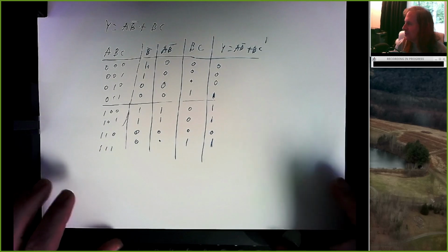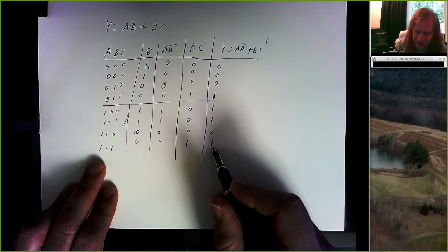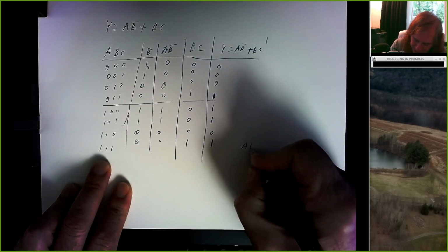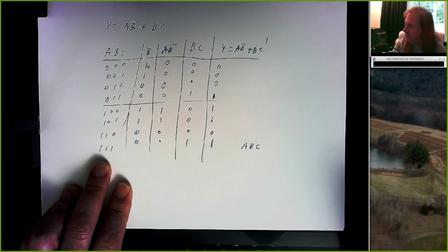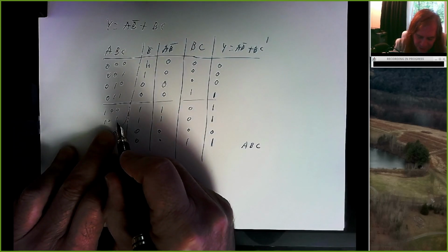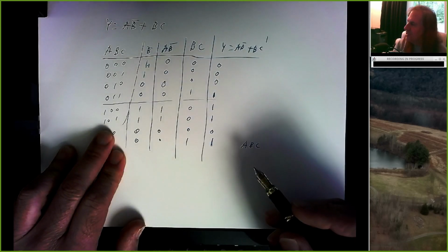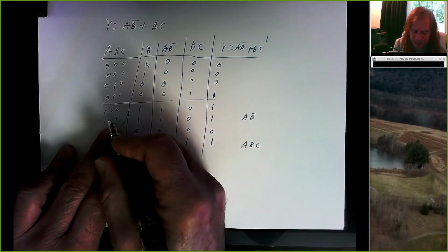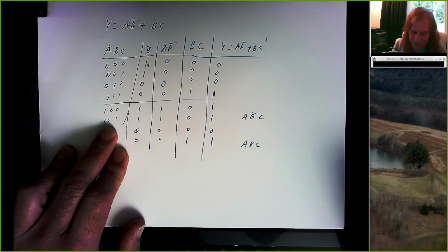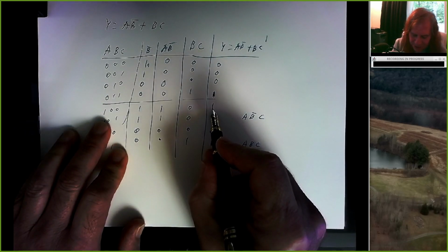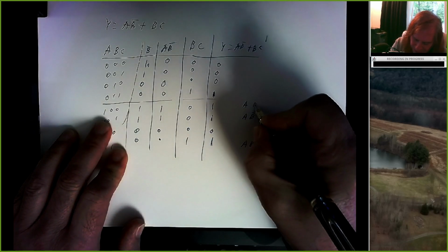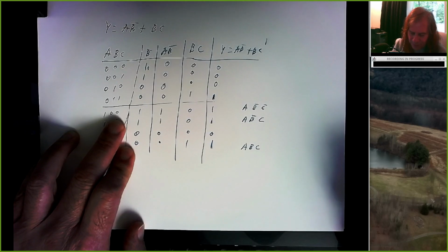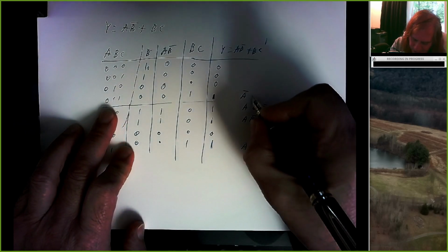This goes back to the combination lock circuit that we built in the beginning. Remember, if we wanted to unlock our cookie jar when the input was 1, 1, 1, if we wanted a 1 here, we said, oh, well, we can just use an AND operation. Let's just take A and B and C. If we're giving our friend a code 101 and we want that to unlock, well, we can express that situation as an AND also. But the AND is we want A to be 1, and we want the complement of B to be 1. We want B to be 0, so B bar would be 1, and we want C to be 1. And this row right here corresponds to the situation where A is 1, and B bar is 1, in other words, B is 0, and C bar is 1, or in other words, C is 0. And this term right here corresponds to A bar is 1, B is 1, C is 1.